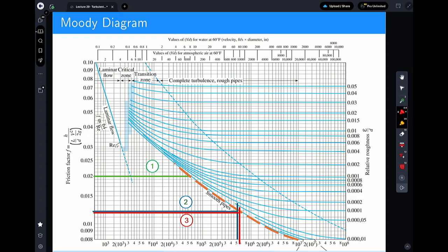You're moving around between, again, logarithmic values, 50,000 to 60,000. Your first iteration is kind of a big guess. You always guess something, and 0.02 often, quite honestly, seems like as good a guess as any to start with. The convergence happens very quickly.